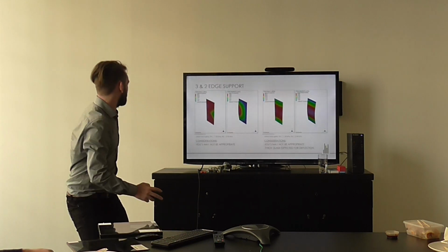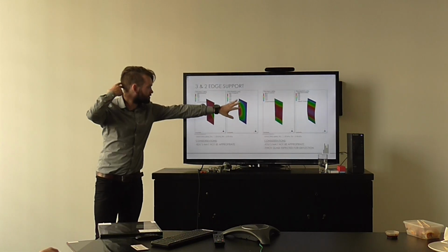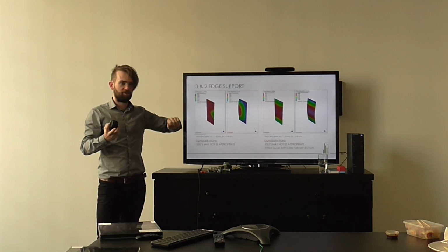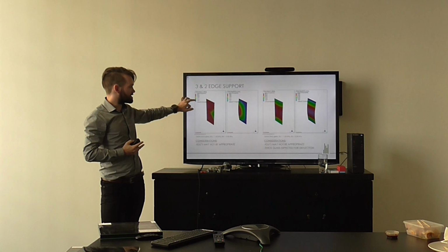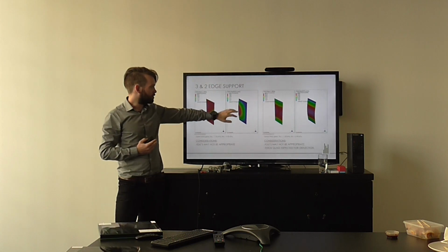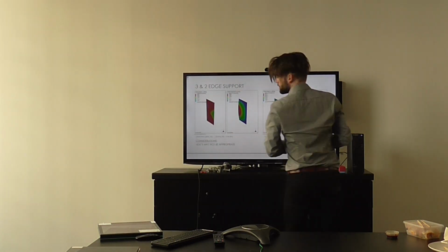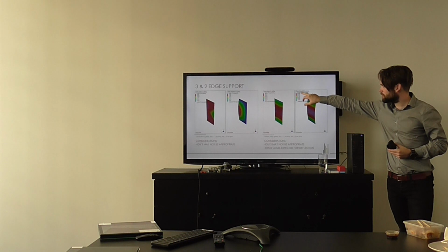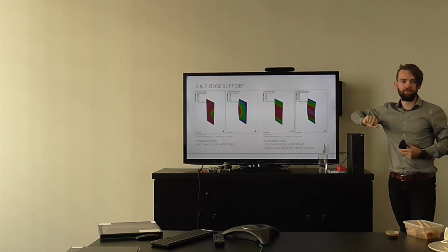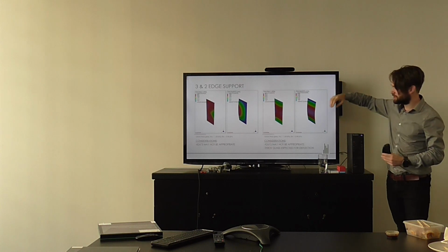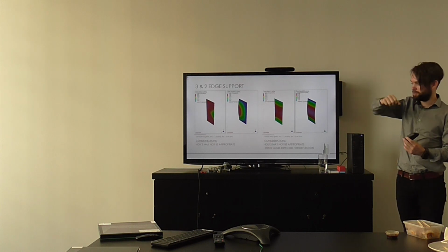So, as before, the images on the left in the two cases are for stress, and the images on the right are displacement. So essentially, they're just referencing the scale here, showing what that is. The pink, if I look at the two-edge support condition, indicates displacement of 43 millimetres, whereas the blue indicates displacement of 0 mil.